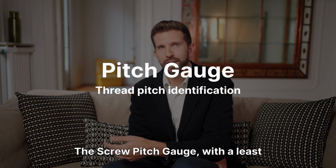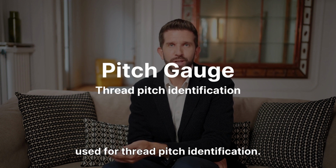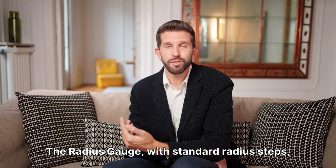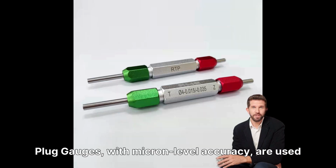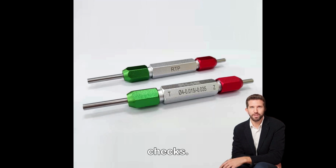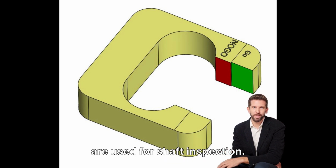The screw pitch gauge, with a least count depending on the pitch set, is used for thread pitch identification. The radius gauge, with standard radius steps, is used for checking fillet and corner radius. Plug gauges, with micron-level accuracy, are used for hole inspection, specifically go/no-go checks. Similarly, snap gauges, also with micron-level accuracy, are used for shaft inspection.